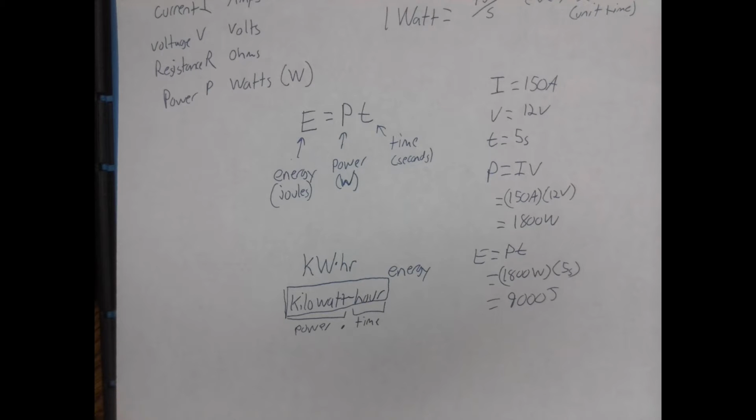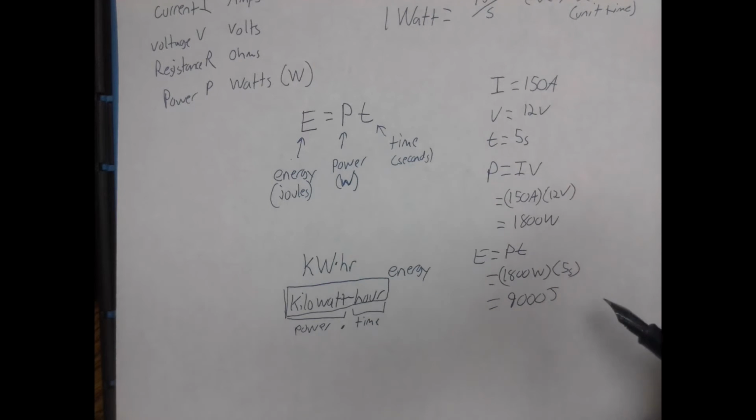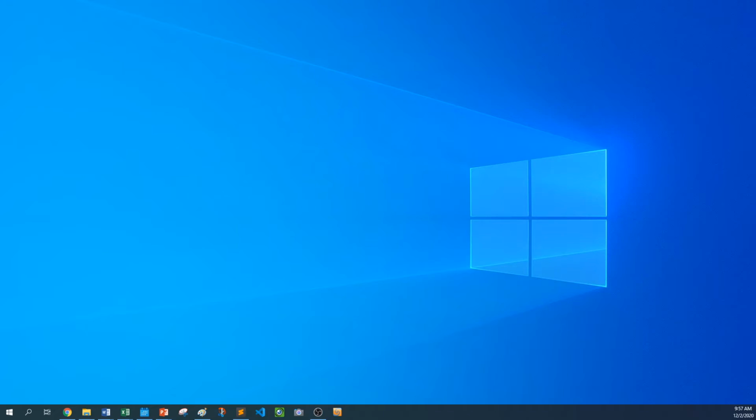So if you wanted to figure out what appliance in your house is using the most energy and costing you the most money, which we will do in this class, we will actually work through a lot of common household appliances. Basically what you do is you figure out how much current, how much voltage is being supplied by it, and then we figure out how much is being used. How are you keeping it on 24/7? Well, then you can do it in joules or you can do it in kilowatt hours, and we can figure out how much energy is actually being used. If it's only used 8 hours a day for a week, you can figure out the weekly cost, and we'll actually look up the price of electricity in Broadus, Texas, and actually get some real values.